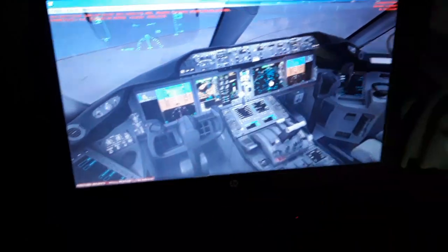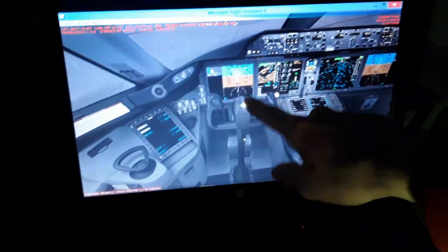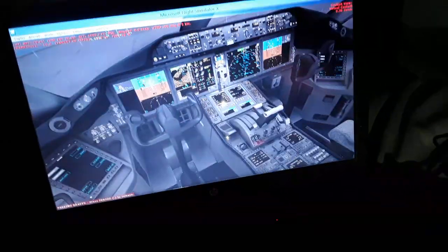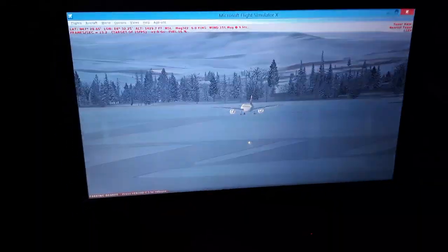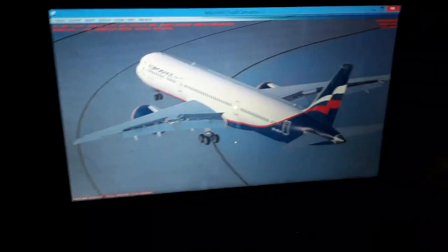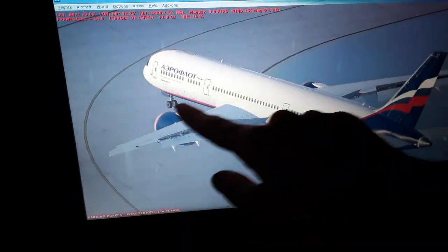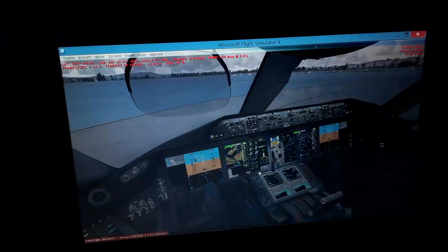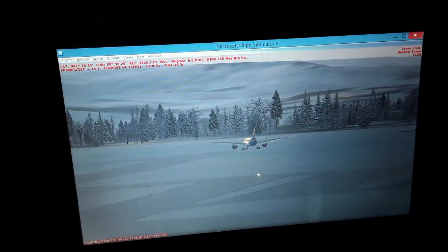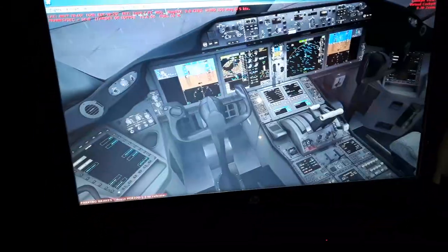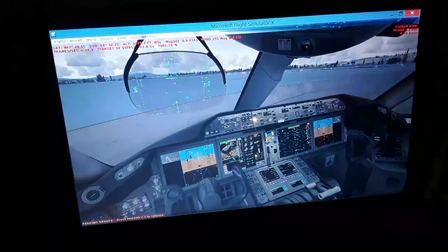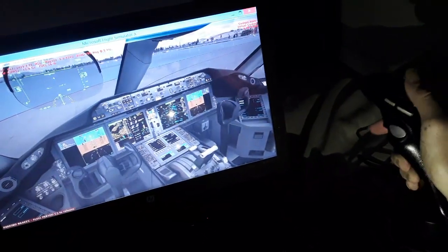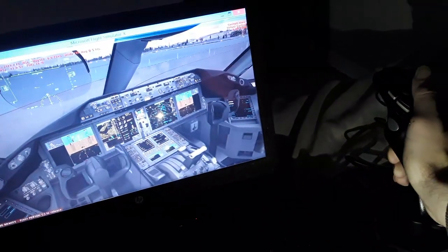Also in the rudder pedals we have the nose wheel steering. The tiller is interconnected with the rudder pedals. It can deflect the forward nose wheel of the aircraft. You can see the nose wheel down here. Over here is the nose wheel of the aircraft, you can see. So you can deflect the nose wheel like 76 degrees left and right until we reach an airspeed in takeoff of like 45 knots. It decreases to 7 degrees left and right. So you can use the rudder pedals to control it.